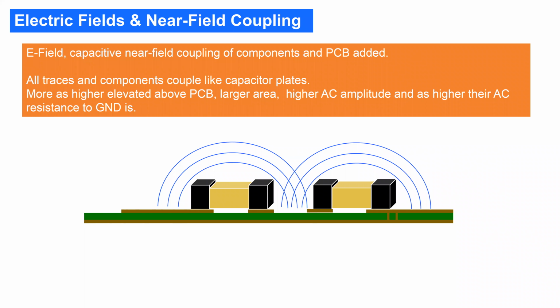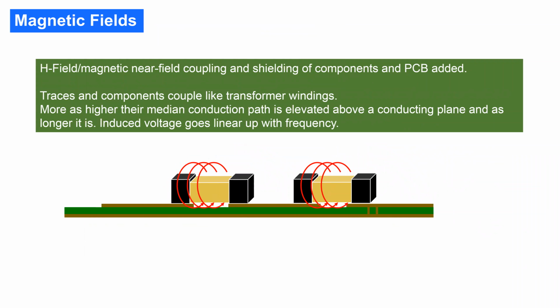In addition, through every part where a current flows, we will have a magnetic field, and this magnetic field will couple into other components in a magnetic way. So we can think that the parts are transformer coupled to each other. For magnetic fields, I will come back to that now. Currents are necessary: the only thing which creates a magnetic field is a current, and the higher you rise the current above the PCB, the further these magnetic fields will reach.